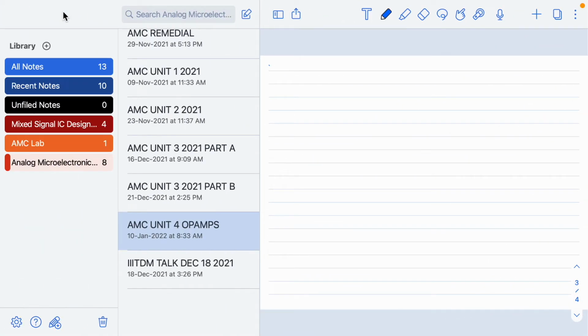Moving on, let us also see what you understand by differential signaling and single-ended signaling. In general, say I have a voltage source and I am taking output from it. Say this voltage source value is Vs, and if I am measuring the voltage across it, how will I generally measure? I will measure from this point with respect to a reference point, and in most cases we consider the reference point as the ground terminal. So if I am measuring a voltage with respect to ground, we call this a single-ended signal.